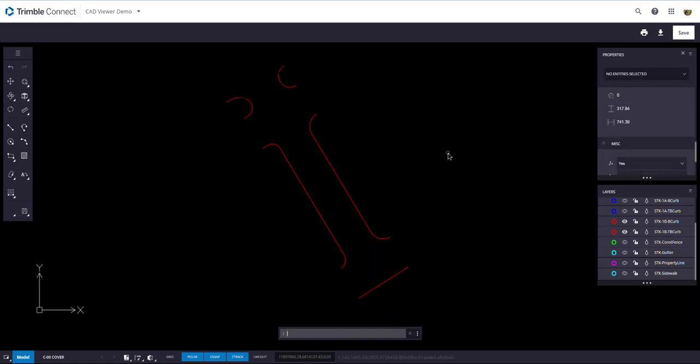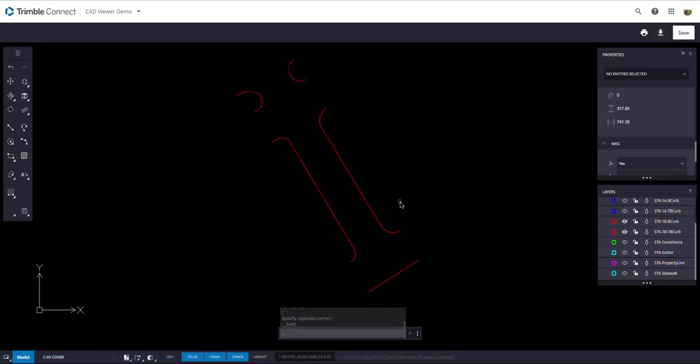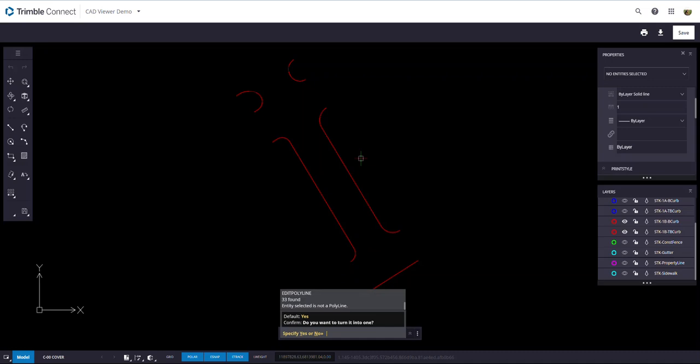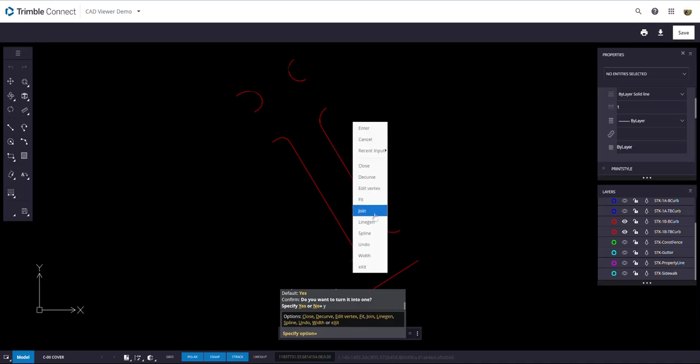Now, you could hit save at this point. So let's go ahead and hit save. So we save the changes there. Now we'll select all these objects and we will do the p-edit command. Again, we're going to do the p-edit, edit polyline. We're going to turn them into polylines because they were either arcs or lines. We are going to right click and select join.